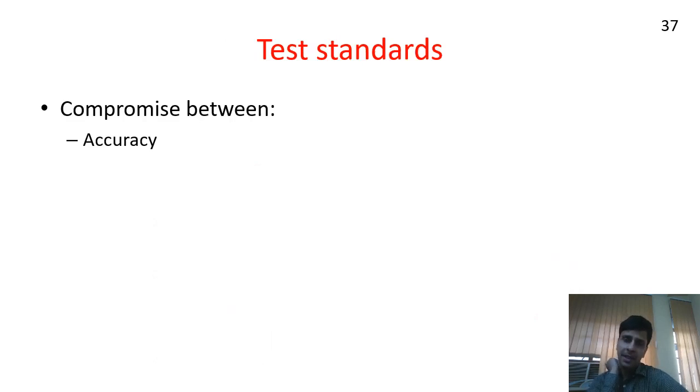So keeping all this in mind, now there is a requirement for a test standard. Let's say you test some material in Nigeria, I test the same material in India, somebody else tests the same material in the US. We should have trust among each other. I should believe that the tests done by so and so in XYZ lab is representative of the material, so that all of us do the tests in the same way, and then nobody needs to do all the tests by himself. He can simply say, okay, so and so has followed this standard and this is the property. You can take that value for your design.